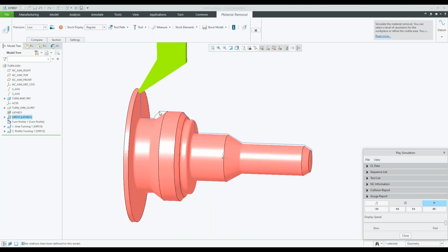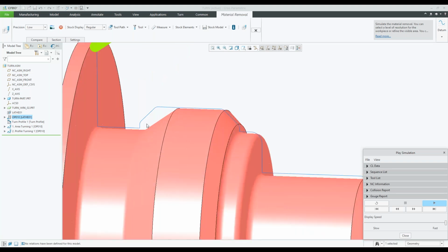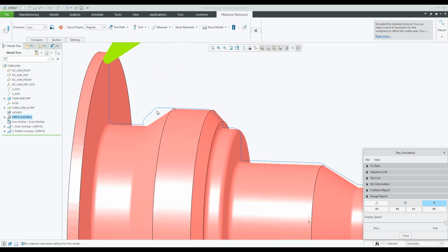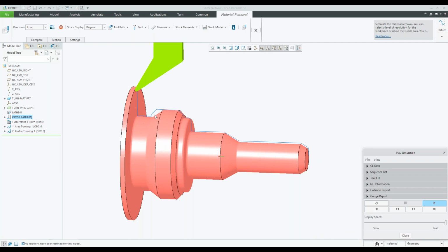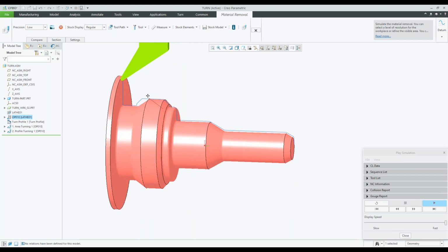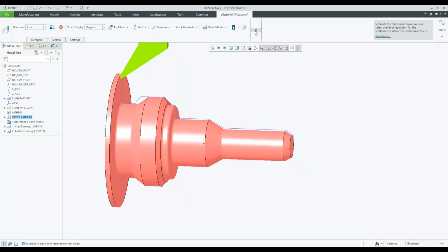No, that finish one, see, I didn't change that. See, that tool can't get in there as well. So that's actually a gouge. If I added my gouge, stop at collision or gouge in here, it could have stopped over there. Okay, so not ideal machining, but we need to set our parameters correctly.